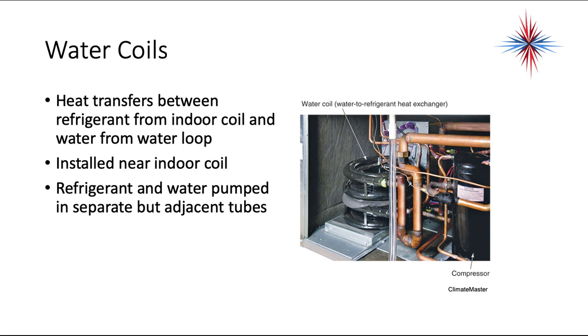Water coils, heat transfers between the refrigerant from an indoor coil and water from the water loop. It's installed near the indoor coil. Refrigerant and water are pumped in separate but adjacent tubes. Sometimes one tube might be inside the other. Okay, it's a water to refrigerant heat exchange.